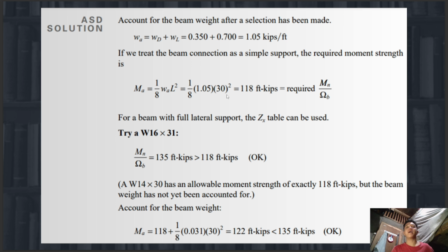Plug in na nato yung mga 118 feet kips. So, it is equal to the required Mn over omega. So, for a beam with full lateral support, the ZX table can be used. So, mag-try ta datong table sa ZX na naka-specify sa beam with full lateral support.